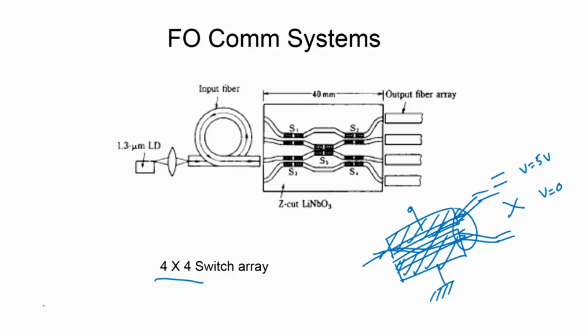When a signal is input at any particular port, or in fact we have signals at all the ports, they have to be exchanged at all the ports. We can represent this by a matrix of elements. For example, let me say the columns and rows represent different input output combinations.